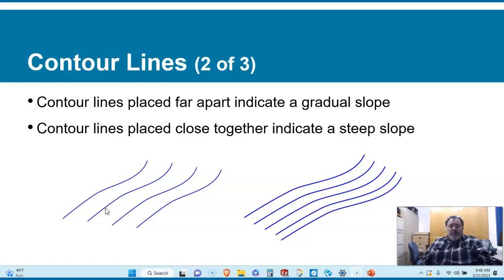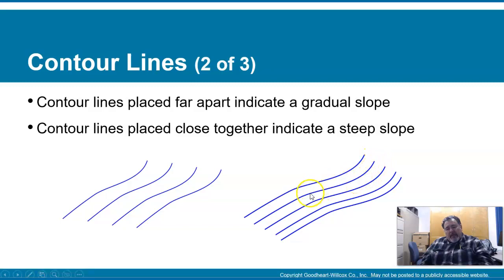So these are examples of contour lines. You see how they move and they change shape. They change shape, but they're following a certain elevation. If you look at this, you can imagine that this is the top of the hill, and this is a higher elevation. Let's call it 20 feet. And then this line could be 18 feet, and this line could be 16 feet.